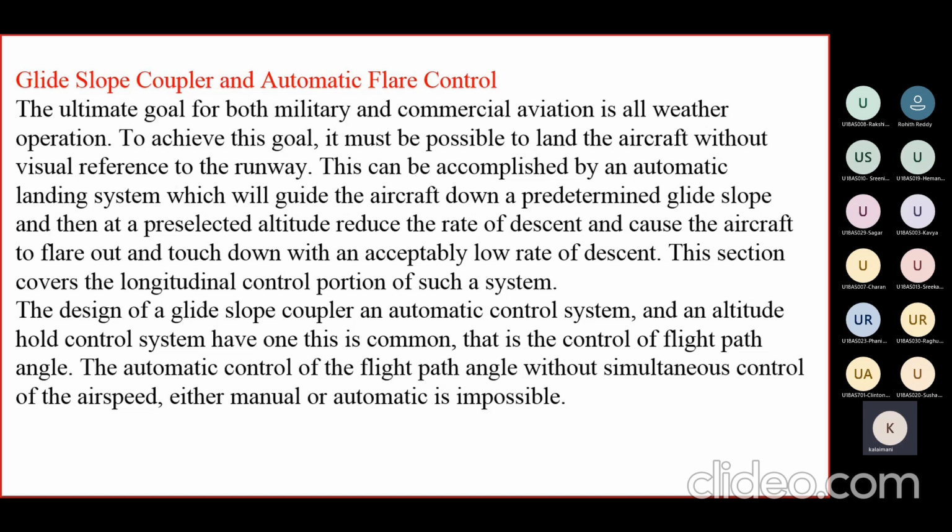Okay. So if you design a coupler, if you design your automatic landing system, you must concentrate on the velocity control of your aircraft. Whether we provide velocity control through manual or automatic systems, you must control the airspeed of the aircraft. Okay, so this portion we are going to cover today.